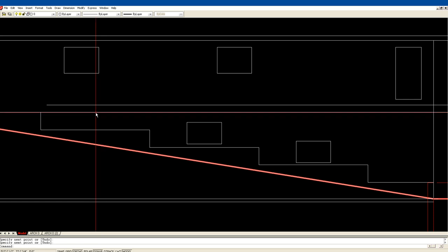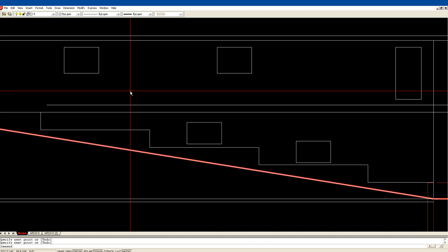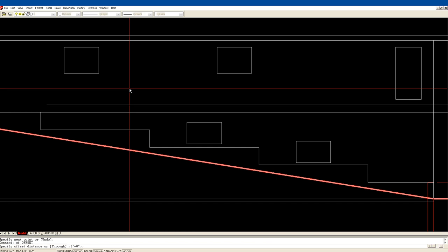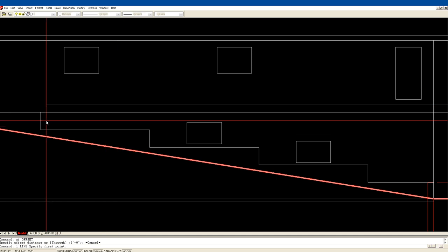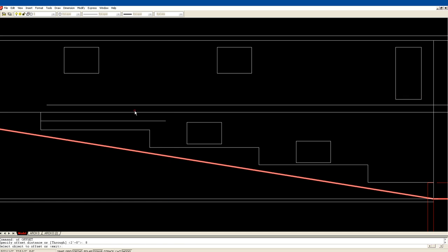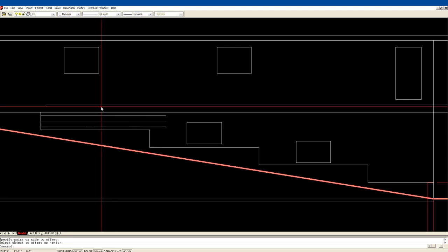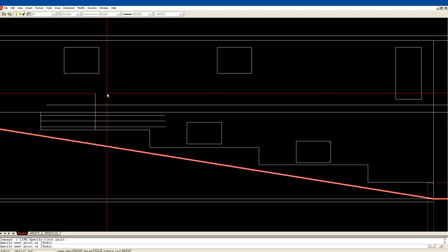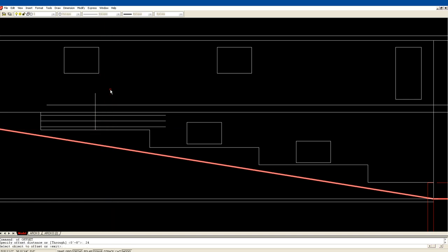Now we can work from the bottom of the floor, and if we offset, give it a plate, we could get a 1-foot window in there. Let's try that. Let's just go in the middle here. And even bigger, let's offset 8 inches. So we've left that much from the bottom of the ceiling for trims and the drywaller to finish this drywall. Let's just draw a line up through the center of this. Offset 24. Fillet.